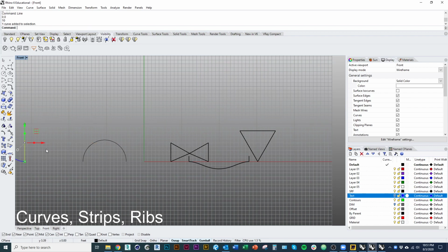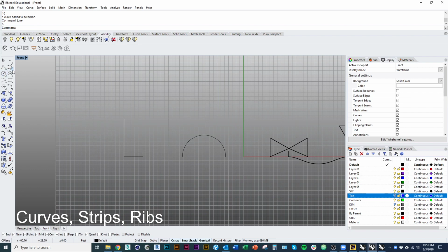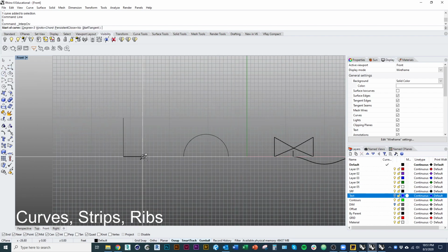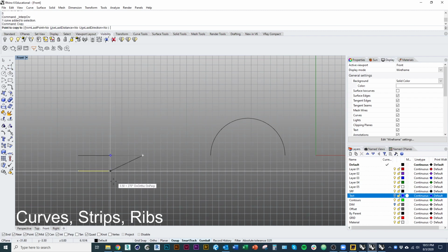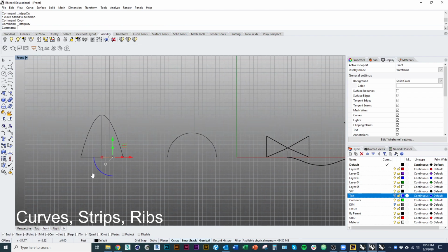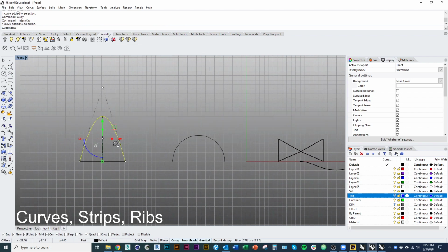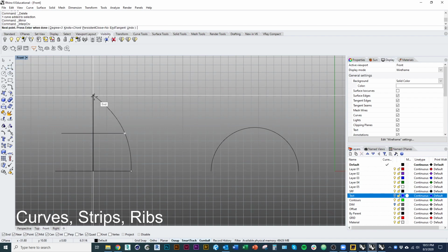So now I have a construction line. And then I could do the same for the width of my arch, so over 5. Okay, and so what I would do here is use that same interp curve command. Oops, and let me just copy this to both sides. And I can do this kind of thing, draw an arch like that. Of course, you can also give yourself more points. We wanted our second line to be like there. You control the number of control points that define the curve.